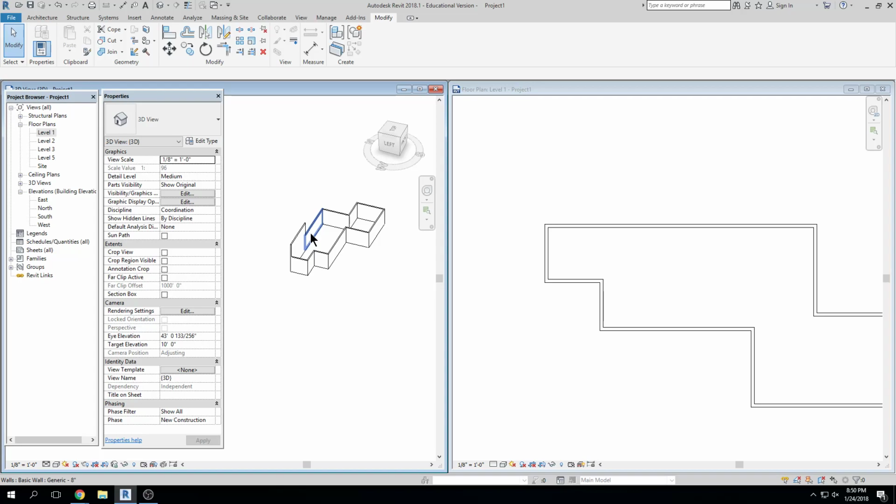So yeah, you'll have a couple of levels or a couple of data markers for each level. And then the roof, of course, and then down here. And actually, so walls are only height-wise constrained with levels? Yeah. It doesn't matter if something is in between and is going to conflict with it? What do you mean in between? Well, like in this instance, let's say the base of the wall is the basement slab, right? And then we just say go to level 1. Right. And it's going to go through the joint.